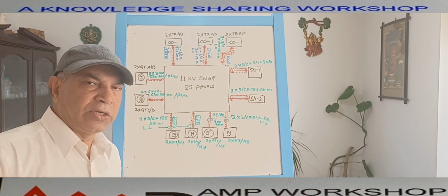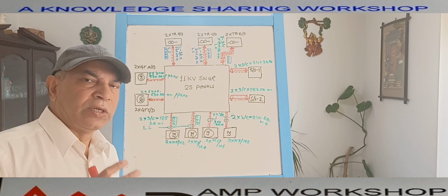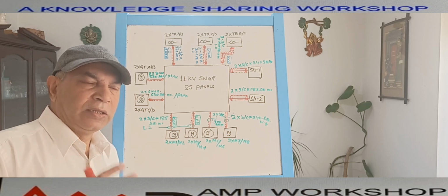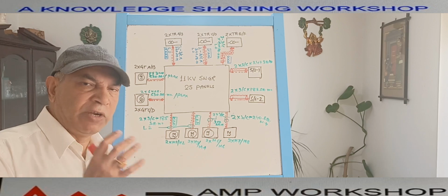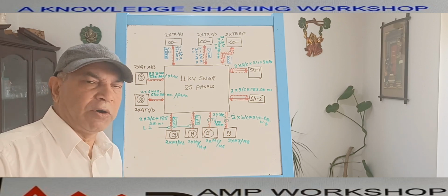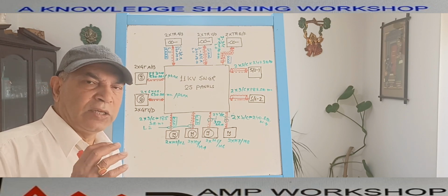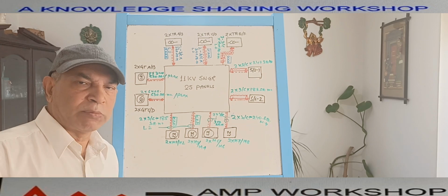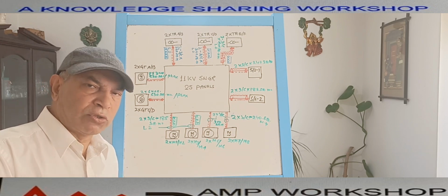Now the power electrical cable is again divided into parts. One is the voltage grade cable for which the switchgear is designed, which carries the major power to the various field equipment. Then there is another category, a small low voltage power cable, which supplies the various AC and DC control power to the switchgear.